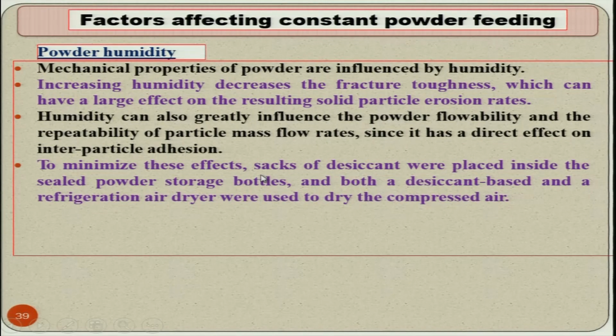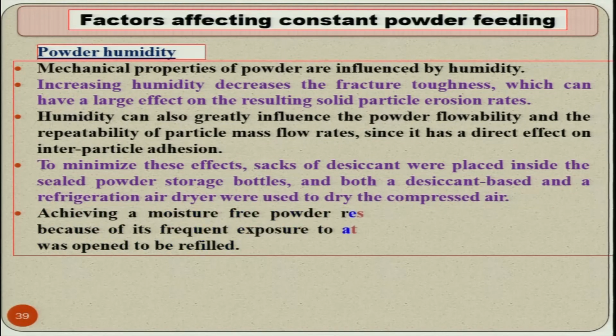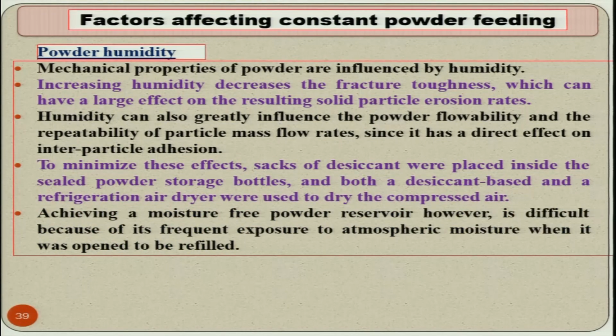To minimize these effects, sacks of desiccant were placed inside the sealed powder storage bottles, and both a desiccant based and a refrigeration air dryer were used to dry the compressed air. So, removal of humidity from the air as well as the abrasive powders is important. Various measures are taken to take care of it, just like the desiccator as he mentioned,